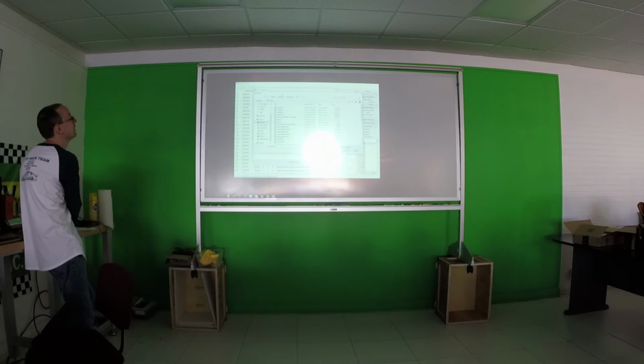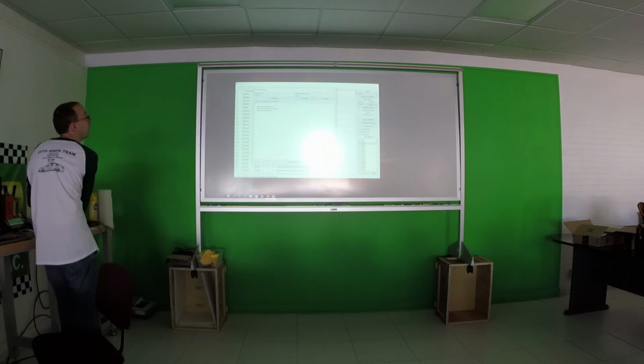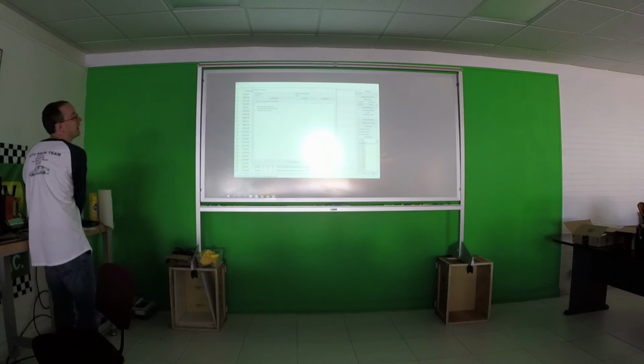File comparator. Let's say my file of interest is this cruise 1, the first time Jack turned cruise control on in the car. I'm going to load up no cruise as the reference. This is what I was saying before, how you might sometimes want to compare when you didn't do something to when you did do something. In this window, you can load as many files as you want for reference. I could load up park to reverse on the reference too.